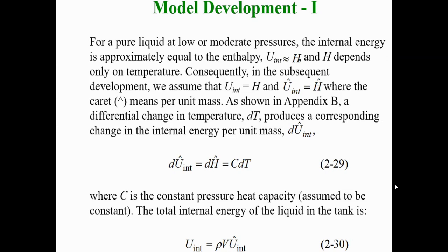We look into examples, model development one. So for a pure liquid at low or moderate pressure, the internal energy is approximately equal to the enthalpy. So the internal energy U internal equals the enthalpy H, and H depends only on temperature. Consequently, in the subsequent development, we assume that the internal energy U equals H and U caret internal equals H caret, where the caret, not bar, means per unit mass.